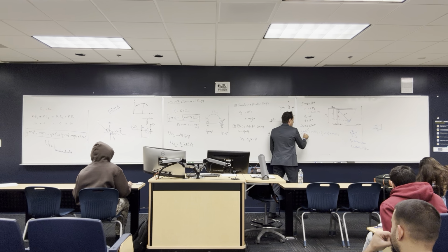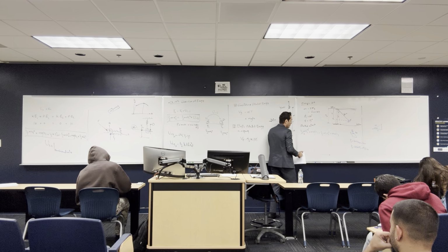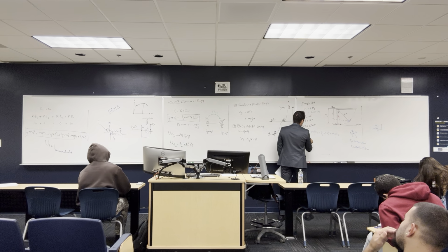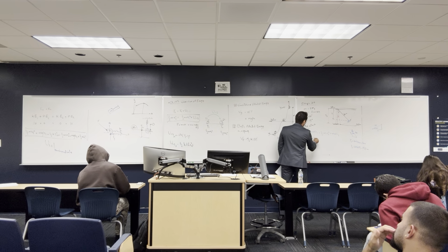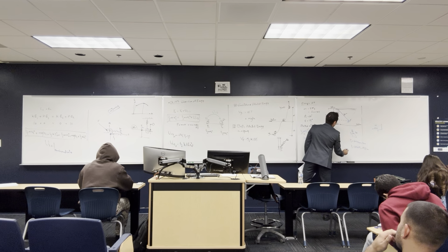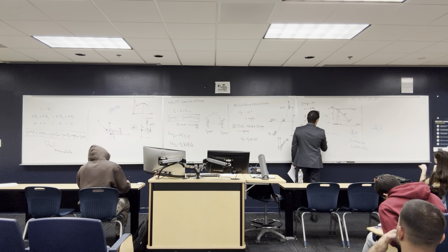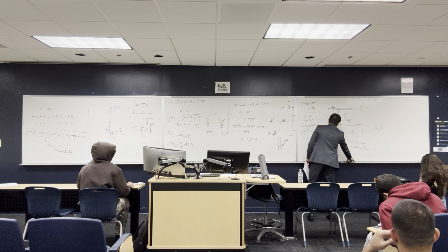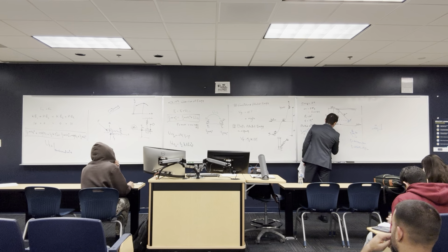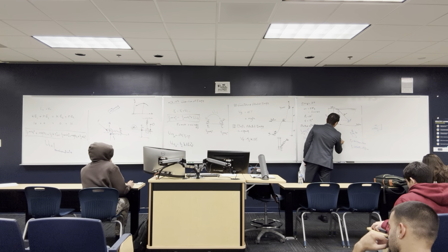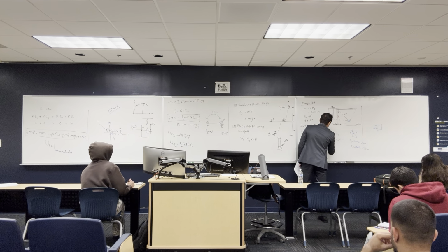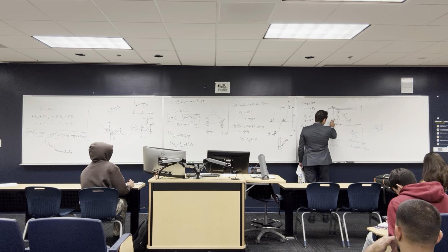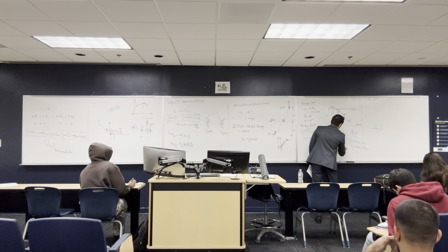I have mv1 is equal to 0, because V1 is equal to 0. And right now I can say that the mass, which is 8,000 kilograms, multiplied by g, 9.81, multiplied by h1, which we just got, 10 meters, equals half m, which is 8,000 kilograms, V2 squared, I don't know what it is, plus m 8,000, g 9.81, h2, which is the new h, 19.31.